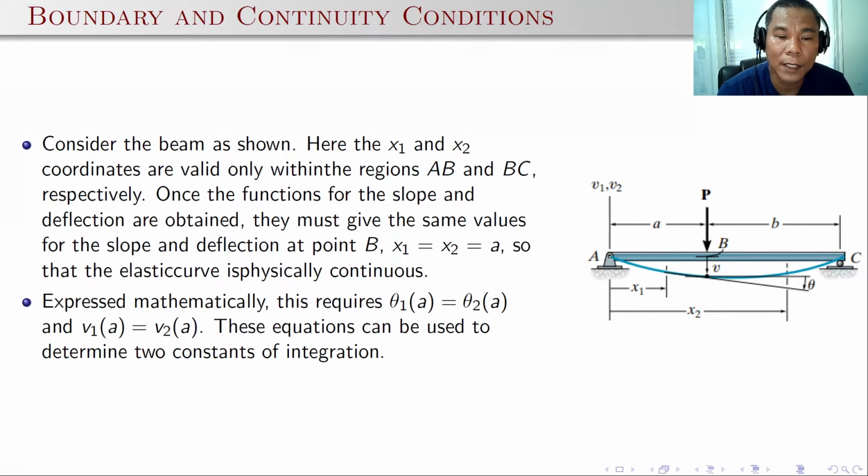Expressed mathematically, this requires that the angle of rotation theta 1 is equal to theta 2 at the same distance a, and the displacement should be the same, v1 and v2, at the distance a. These equations can be used to determine two constants of integration.